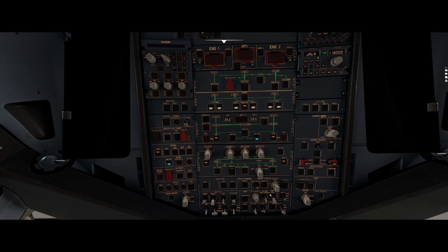So this is just a bit more lighting for the cabin that you don't really need. This is our cabin pressure panel. We have a landing elevation, we're just set to auto at the moment. We have an APU system, an anti-ice system and our probe window heat system. So all this currently, anti-ice can be kept off. This is already set to auto, and the APU can be kept off. The APU is usually turned on before passengers start boarding, and likewise with the APU bleed. So that's pretty much the main overhead panel setup for the time being.